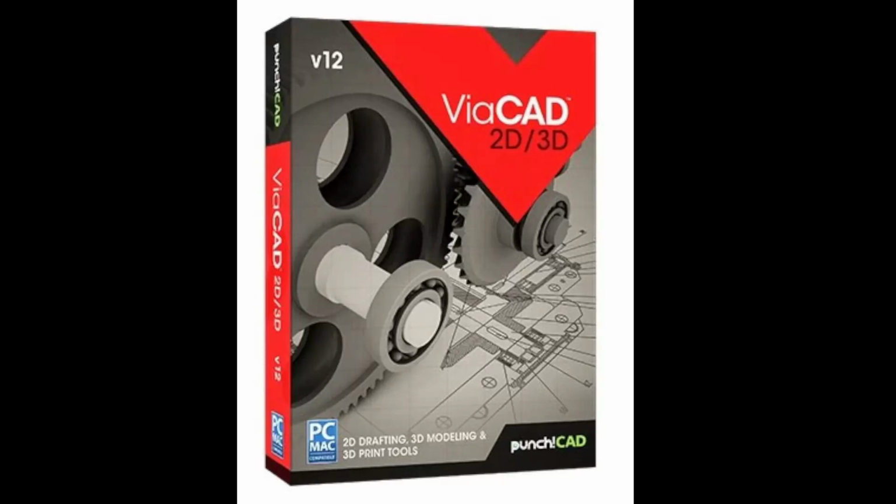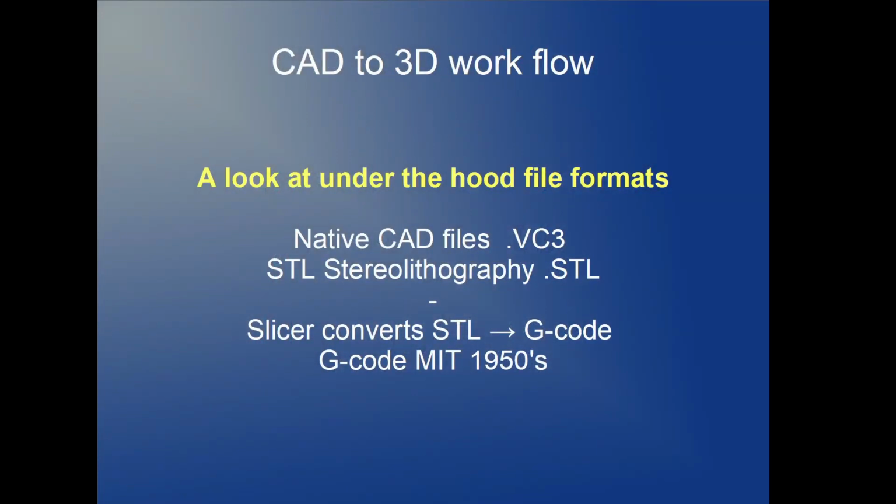So ViaCad V12, the 2D, 3D. And we're going to look at the workflow, and we're going to look at the native file formats. What do you save your files in when you're in a CAD program? What do you export them to? STL files, stereolithograph files, and how do you convert the STL files into G-code with the slicer? And what do you do with those G-code files, and what exactly are those G-code files?